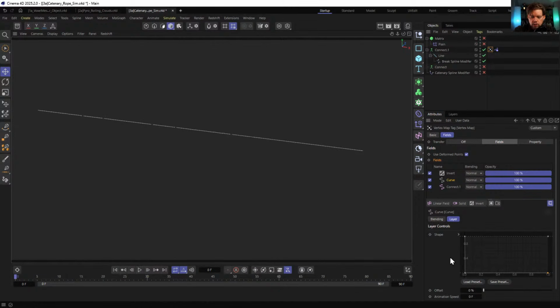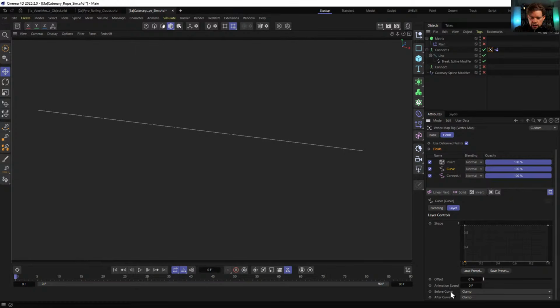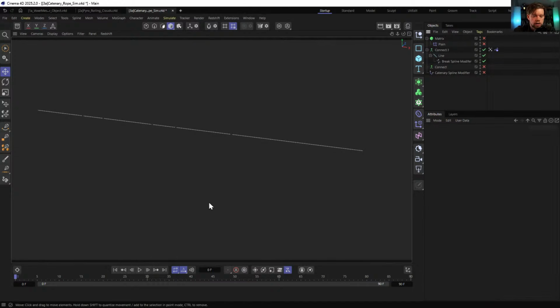Yeah. But one last thing to mention is I could select this point, and then if you go to this twirl down, you can see here's an actual number with the values. And I could say like, oh, it's actually 0.01, and that's the smallest possible number. Grab this one and say that this is 0.999. That's the largest possible number without actually hitting 1 in Cinema. And in theory, yeah, so now we could have like 10,000 points on here and it would never mess up. A little meticulous, but I would be confident that this is going to work for everything we want to throw at it. So that's pretty cool. So now that we've essentially got a working rig, and I will save that.